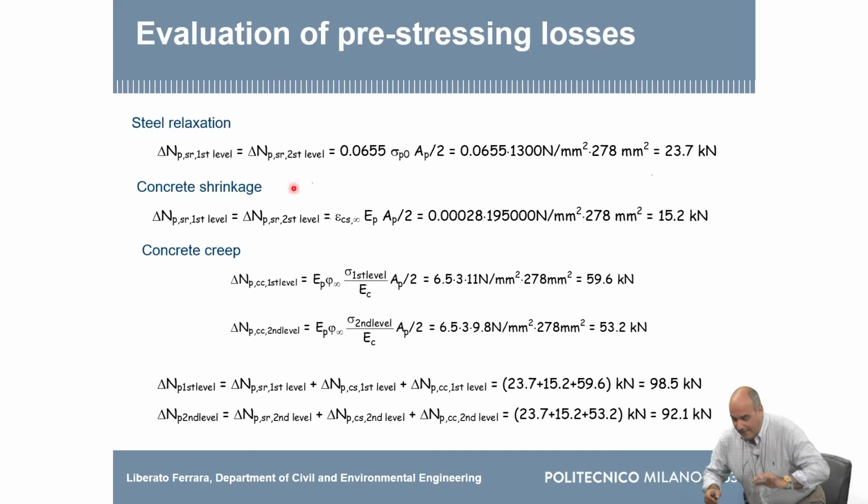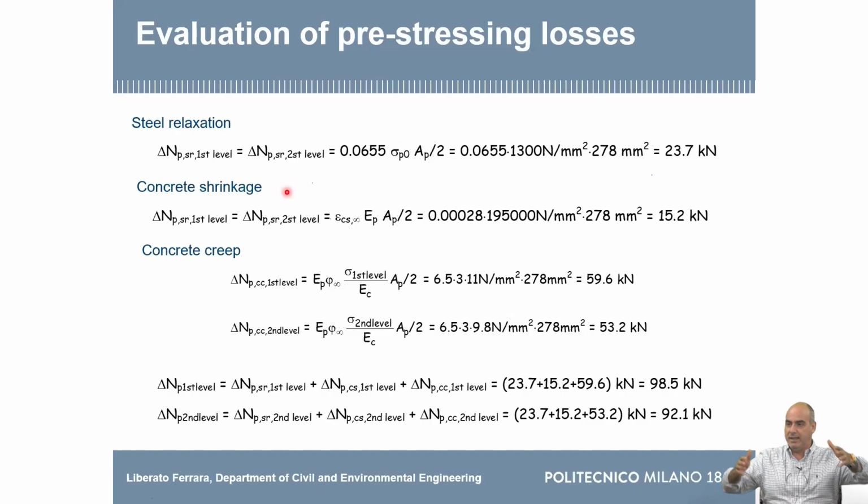Now, the element has been lifted, has been stocked, has been relifted, put on the truck, transported, and so on. So we are ready to evaluate it at time infinite, in its structural design situation. And in order to do this, we are moving from time zero towards service life, towards time infinite. So we have said there are pre-stressing losses. How do we calculate that?